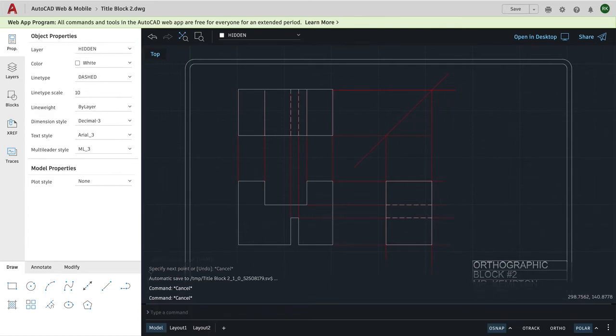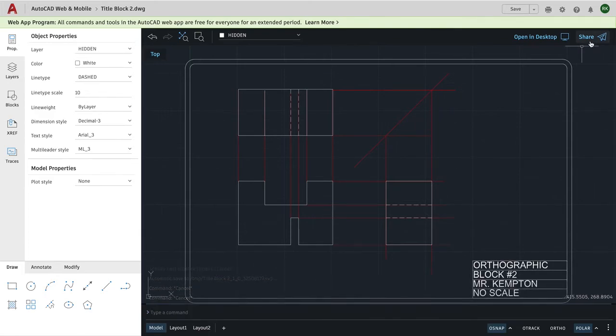Okay, so there we go. Finished drawing. We have 3 different layers. We have accurate lines representing our object. We have perfectly accurate lines representing our projection lines. Information is transferred from one to the other in each view. And we have our accurate 45-degree line that allows us to project this dimension of depth over to our right side. Okay, I hope that goes well.